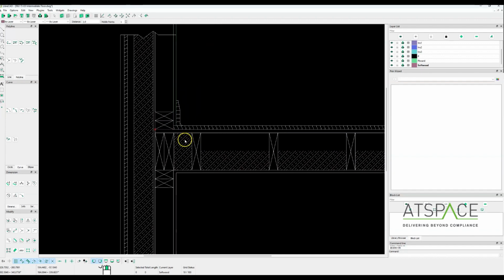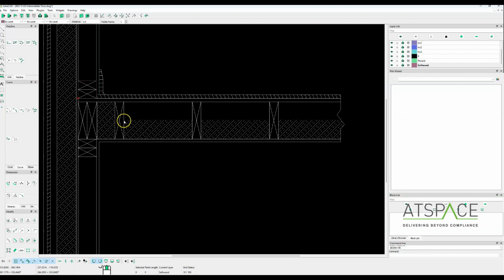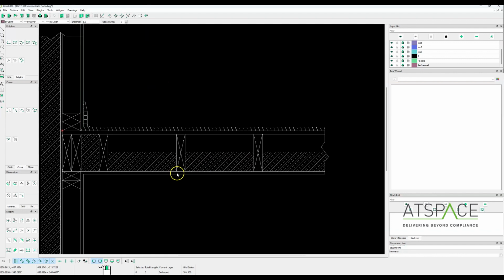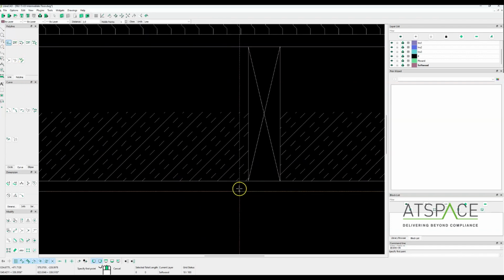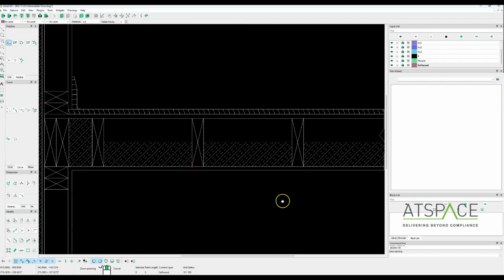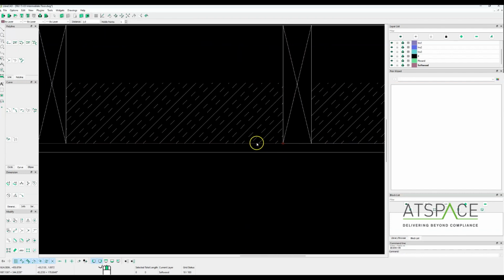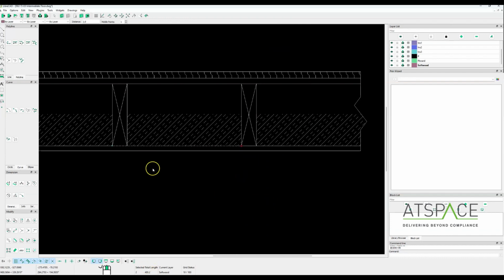Oh, the other decision we need to make here as well is how many of these studs, these not studs, sorry, these joists we want to include in this intermediate floor here. The way we do it in this case is we find out what the distance is between the studs, which I think is 400 in this case. Let's have a look. So we can measure it with a polyline here. Click on that. Yeah, it's 400 mil between the studs.